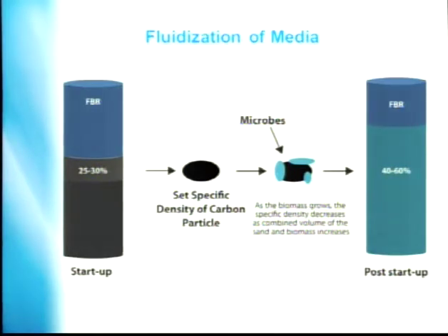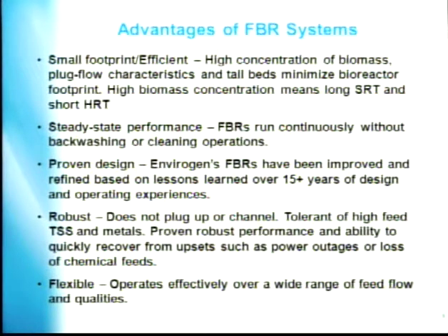And this is where it comes into drinking water, to minimize turbidity and some of the aspects of the surface water treatment rule. So some of the advantages of the FBR systems: small footprint, and you get a high concentration of biomass on this media, typically with plug flow characteristics. So you really get a long solids residence time as the biomass attaches onto this media itself. And the media has macro and micropores, which it can attach to. In terms of talking about carbon, sand's a little different animal there. And then, with that amount of biomass on the media, you can have shorter hydraulic residence times, and you can get steady state performance.